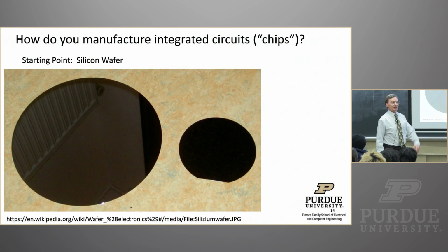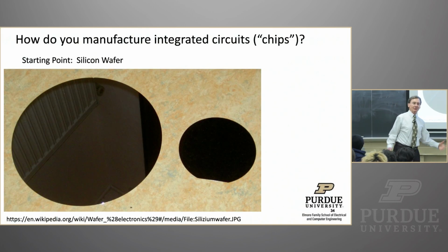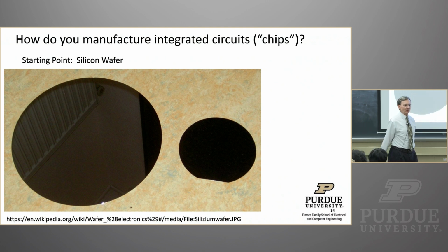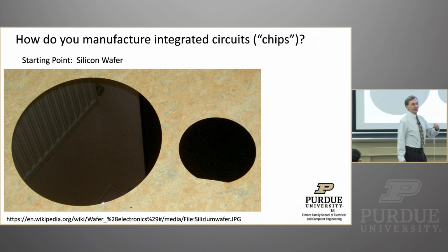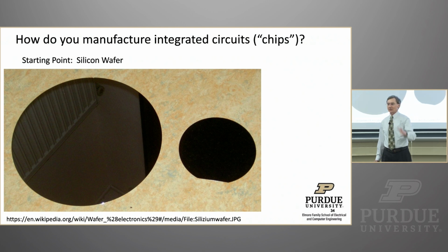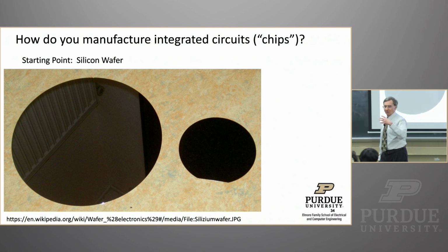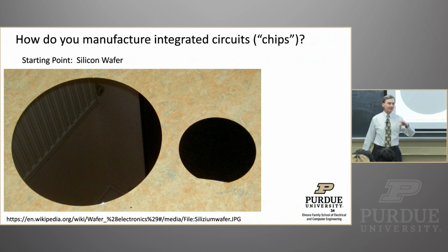Okay, great. So now we've got a transistor. We've got a simple idea for an integrated circuit. So how do we really do these things? Well, it all works based on wafers. We don't ever process a single circuit. What you wind up doing is processing lots of circuits together, right? You have this big parallel process where, not necessarily all at once, but at least in major blocks, you can process the thing through from beginning to end.